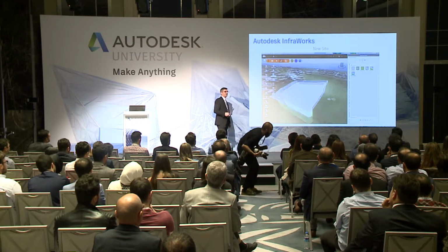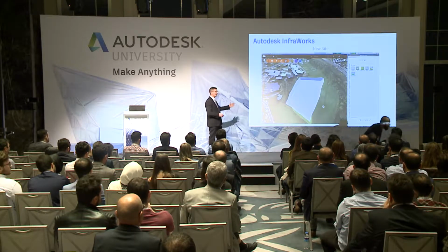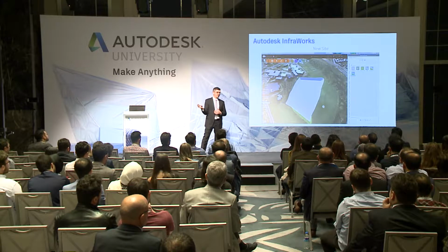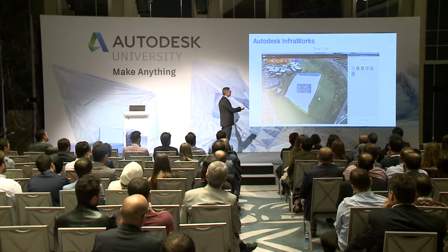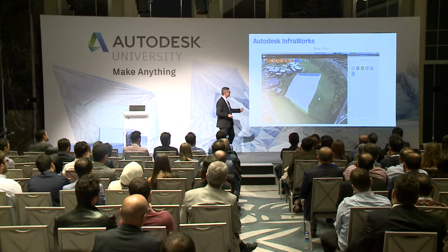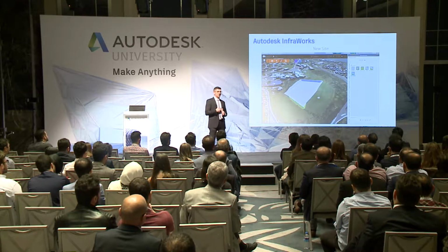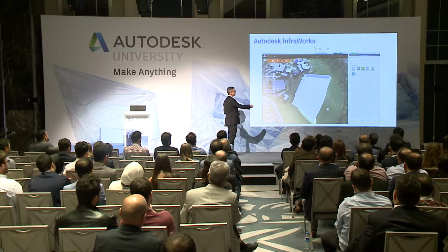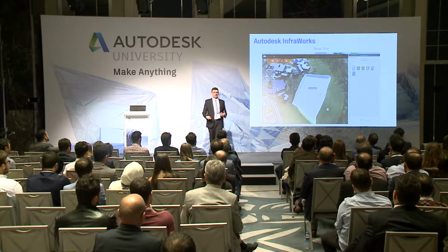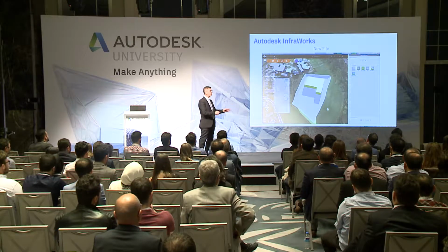Okay? Then we can define different types of material, one material if you are in fill, or another material if you are in a cut situation. And then you can have a sort of query, very fast, to understand how many square meters you have, how many cubic meters you have in this case, to understand the volume of the terrain that you put from your site and go outside.